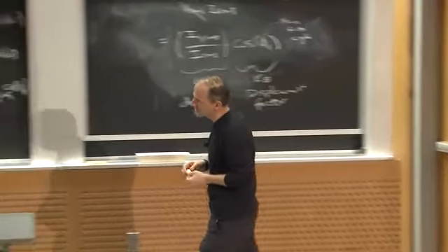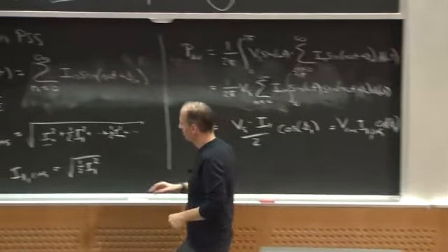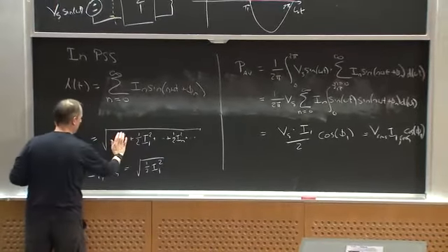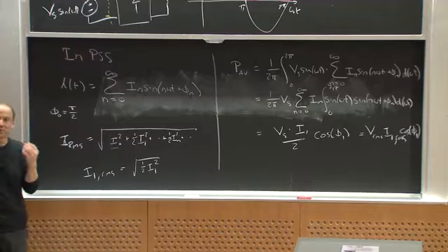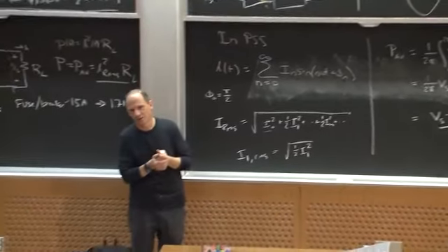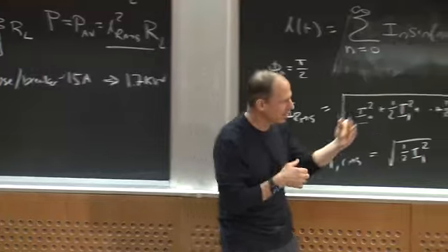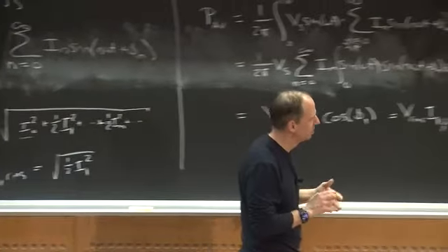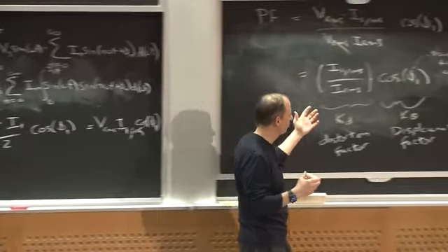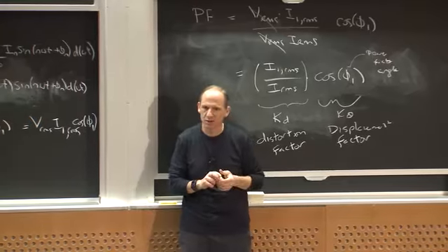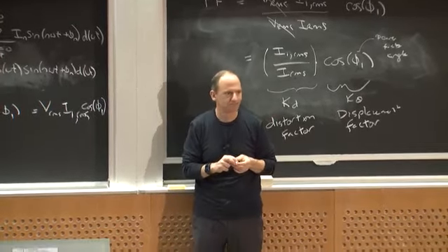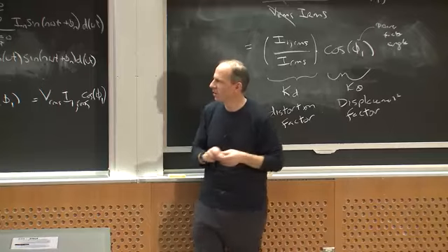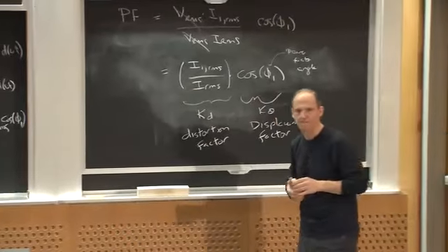Well, if I got rid of the DC component, for example, suddenly my RMS would go down and my power transfer would stay the same, and I'd be a happier camper, right? That might be one thing I could do, for example. But these kinds of calculations can tell you what you should do to get better utilization of your source. Whereas the best thing you can do is look like a resistor. Okay. Any questions about any of this so far?